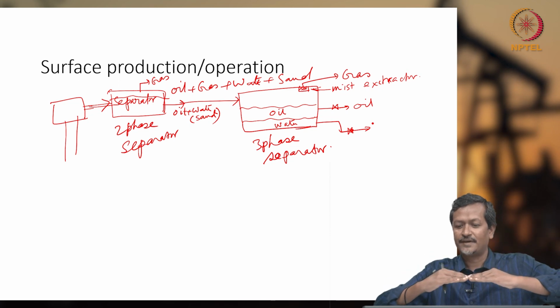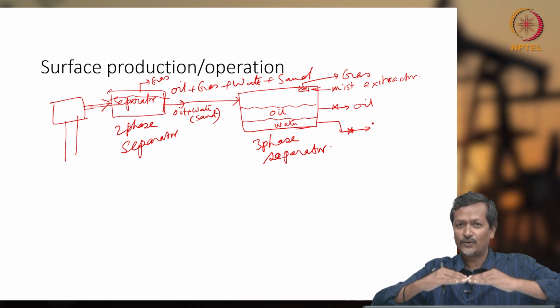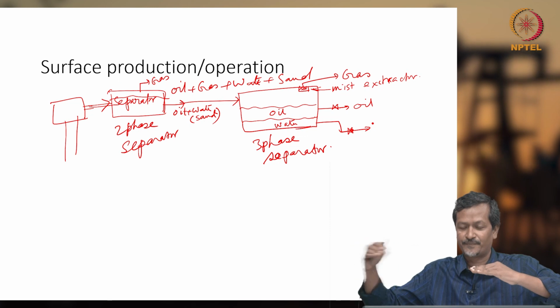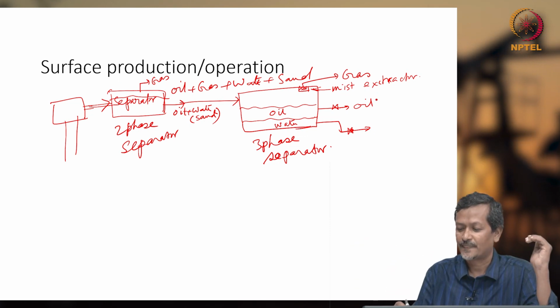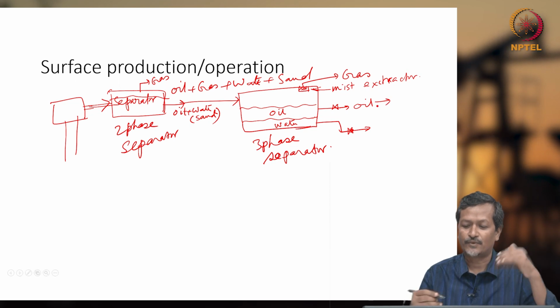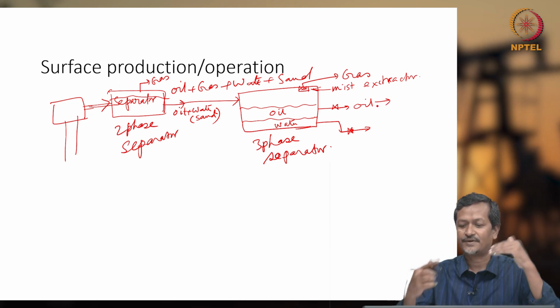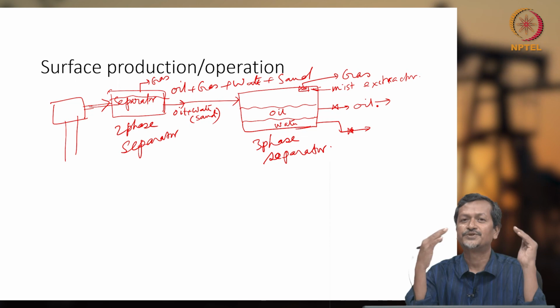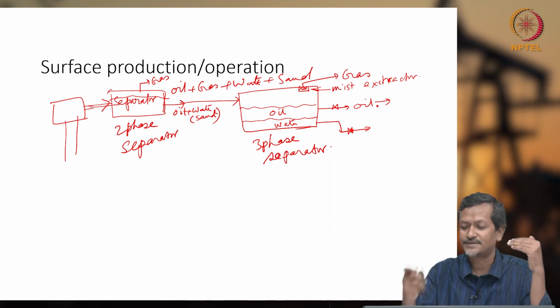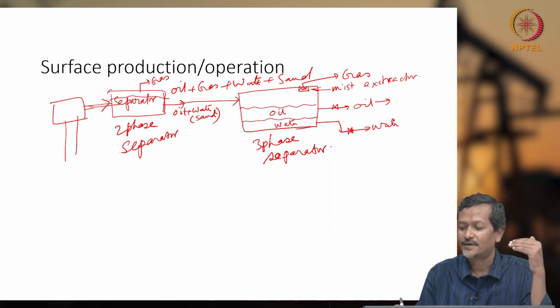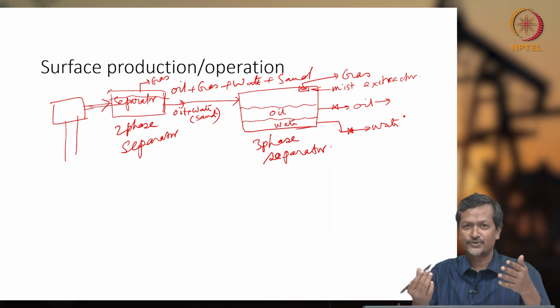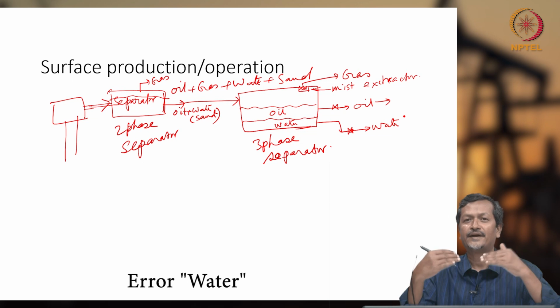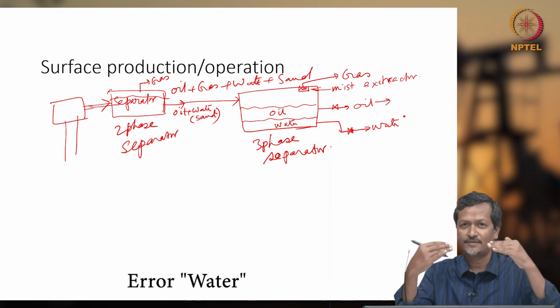After a certain time, the oil level is below the entry point of the exit valve. So in that case, gas will be coming out from your oil channel. So the oil channel will have gas. But if you reduce further, and the water level is almost 0, then in that case your water pipe will have lots of oil, or if oil is also not there, then it will have gas. So, you have to maintain the oil and water level properly.